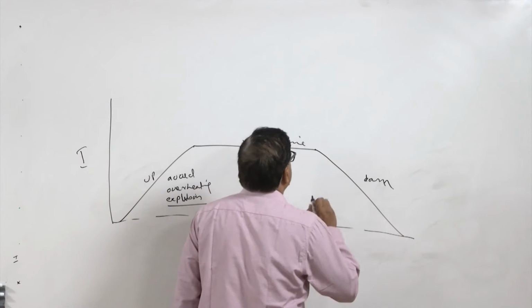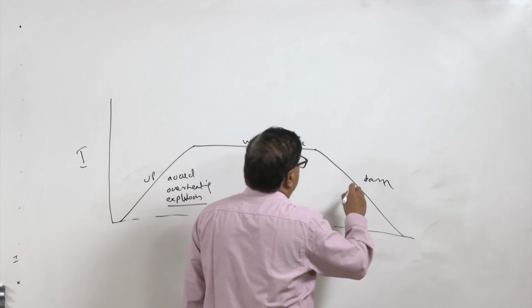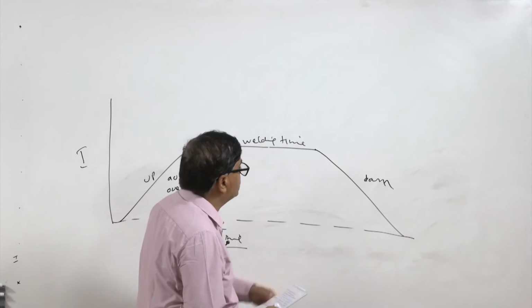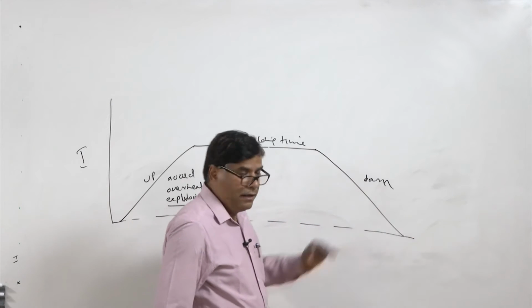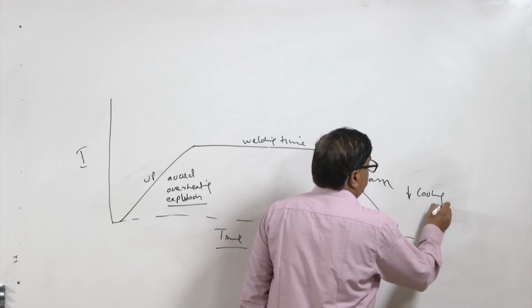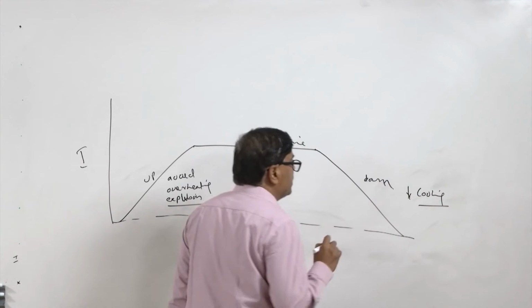Similarly, in the case of the down time, the welding current value is reduced gradually. So, heat generation will be reduced gradually, and this will help to reduce the cooling rate experienced by the portion which was heated during welding.